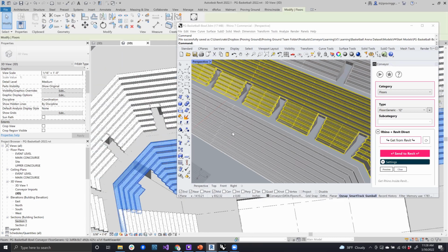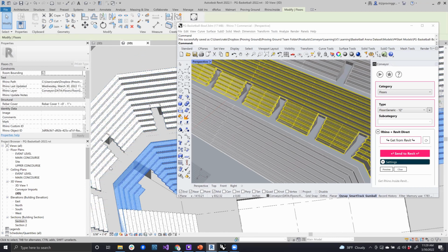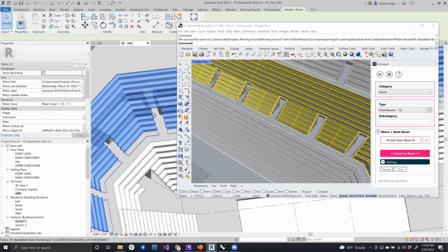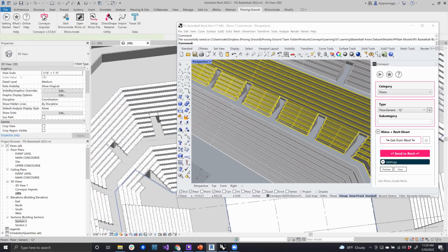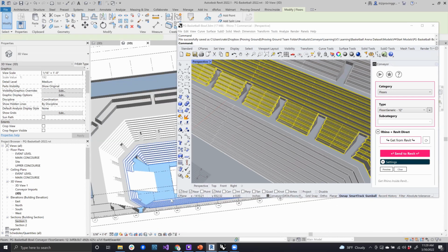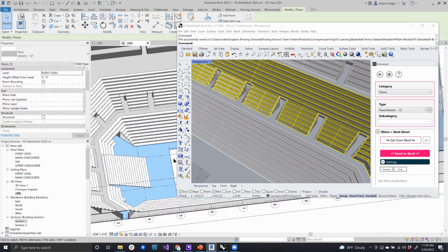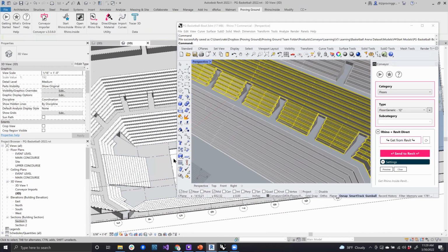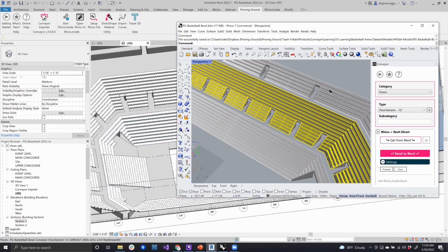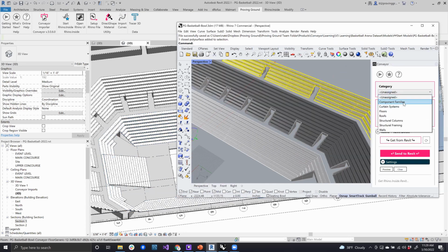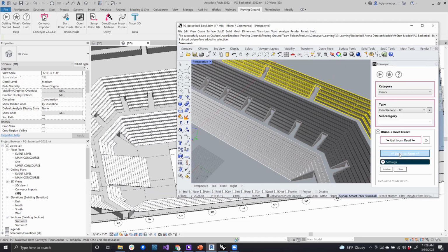We still have to edit things in Rhino and bring it over. When it comes to other types of floors, like planar floors, like the one down here, that have boundary curves, those objects can be supported through Conveyor and edited after the fact. But just to move things along, I'm going to do the upper riser as well. I'll classify that as a floor object and send that over.